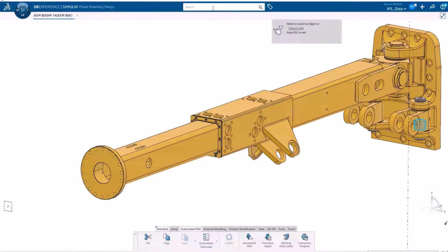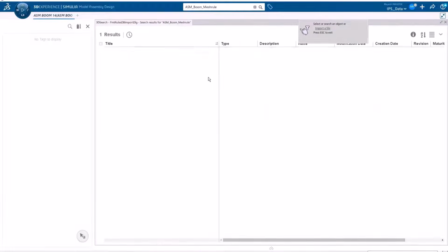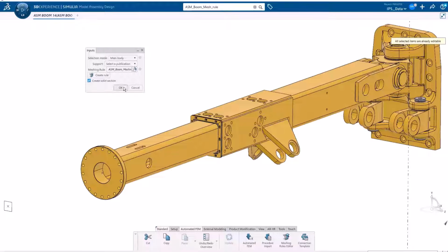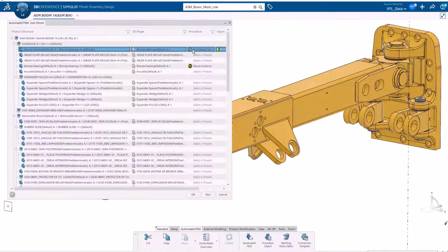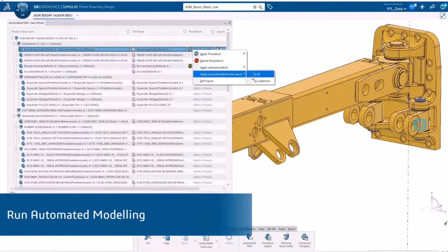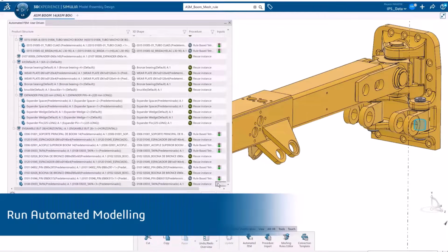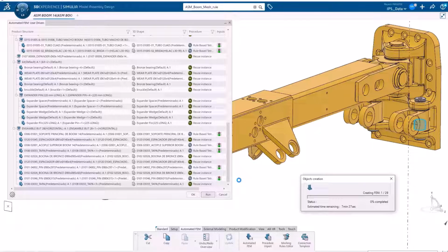Of course, we can set up rules that work globally like this, or we have full local mesh control as well. In this case, I'm just searching it up and applying my mesh rule to every single body, and by clicking Update, my mesh will be generated component by component, taking just a few minutes to mesh every part in this assembly. This mesh is saved inside of that finite element model for these parts that I mentioned,